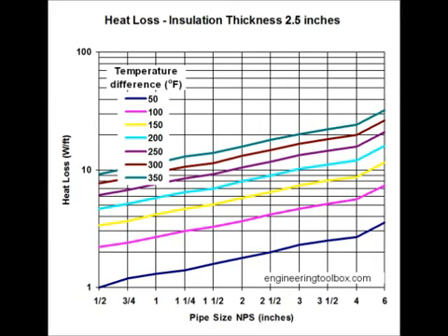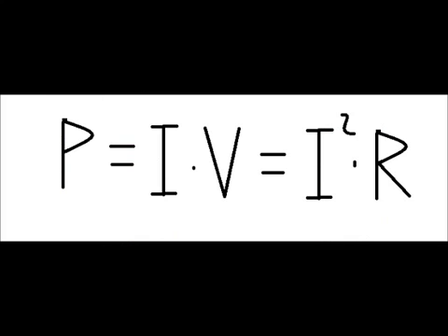In order to achieve greater efficiency, people want to minimize the heat loss, which is the primary energy loss in electrical wiring. So the power is equal to the voltage multiplied by the current. According to Ohm's law, the voltage is equal to resistance multiplied by current. Hence, heat loss is equal to current squared multiplied by resistance.